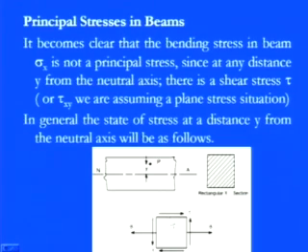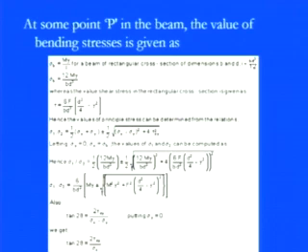With consideration of those things, we can describe the stress components on a simple segment. As I told you, the longitudinal ones are the flexural stresses from bending, and then we have the shearing stress tau. So this is the combination of stresses in a beam with a rectangular cross section carrying both normal and shear stress components. Now, when both components are there, we can easily go for the principal stresses.